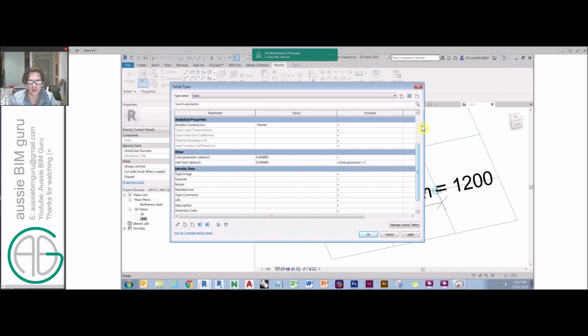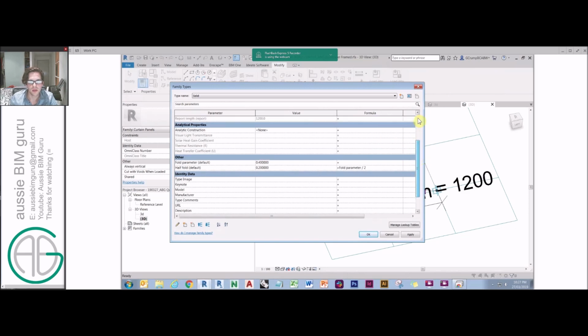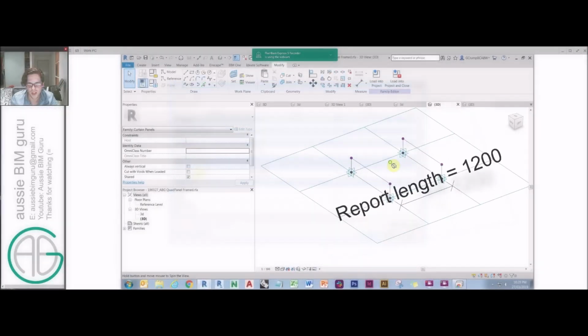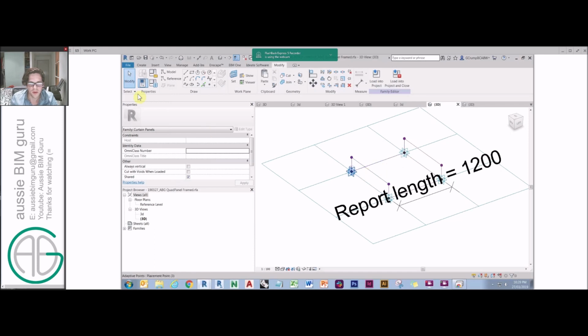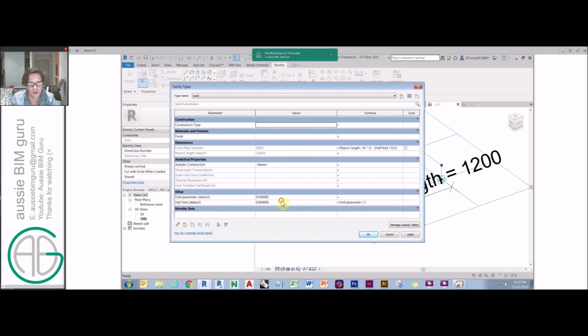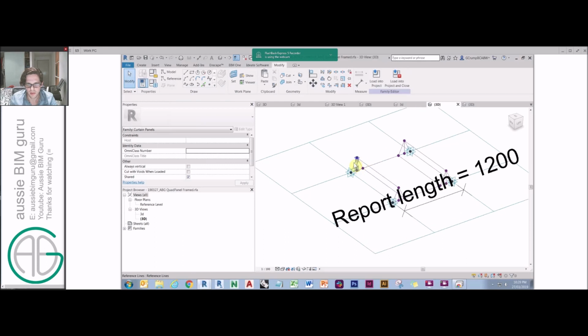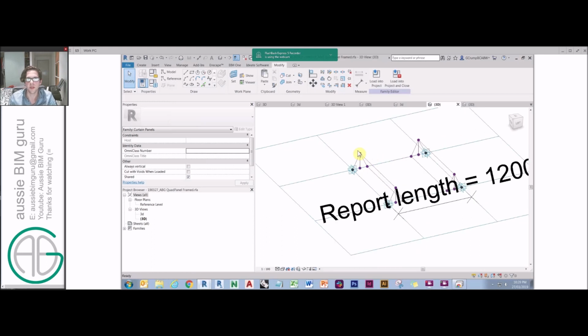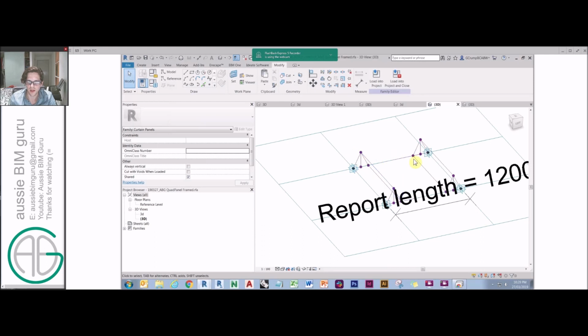And the next thing we're going to need to do is set up the apex to a formula. In principle, that formula is going to use these folding parameters to understand my apex is at 300 when I'm opening my panel, because I have two panels folded together in principle. So we can now say fold parameter is 0.2, and you'll see that apex is basically figuring out how high this needs to be. And in principle, the formula makes sense. You're welcome to have a think about how the formula works, but it's really just figuring out what size these are based on the ratio of how open this is on a factor of 0.5. So we'll move on from there.